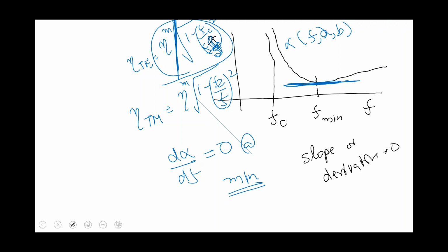I believe Rs is, again, I'm trying to remember, Rs is I believe the square root of pi f mu divided by sigma. Surface resistance, right, sir? Yeah, Rs, surface resistance here.